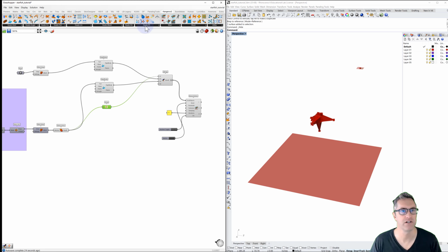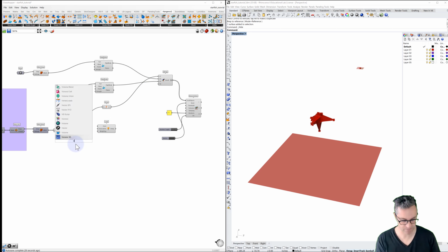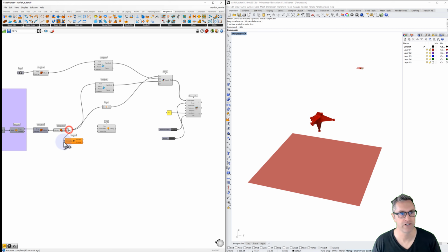So under goals for point, let's use load. And what's nice about this is we're going to use a single point, which is going to be the volume of our unioned mesh, which will be the centroid. There's the centroid point.